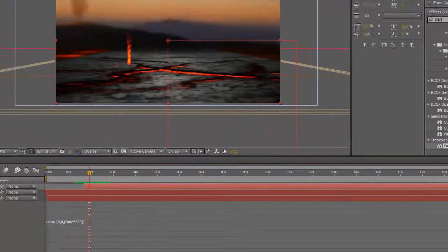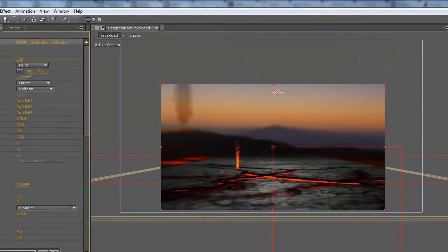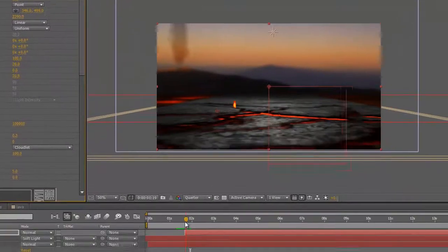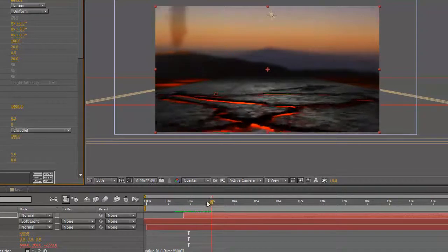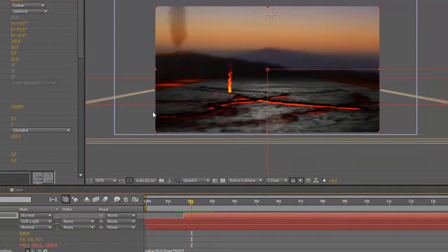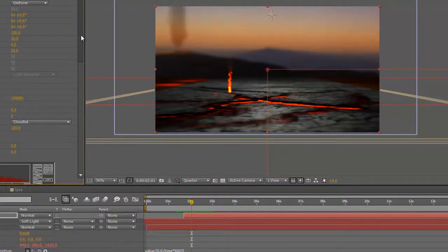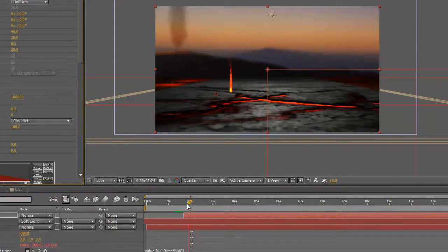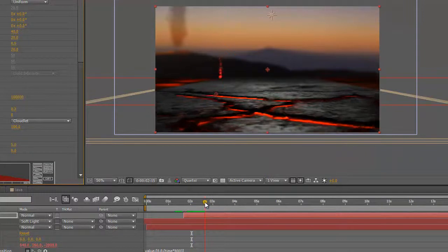I just want to tweak the Z a touch here, just to look as though it's coming actually through a crack. Yep. No, the velocity's too much. It's too fast at the moment, so let's take that down to maybe 40. You'll see more of a flame tail there.